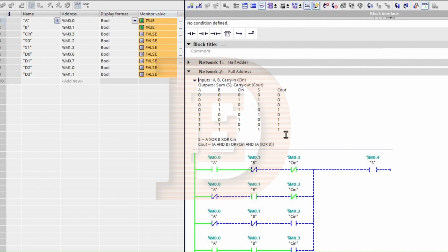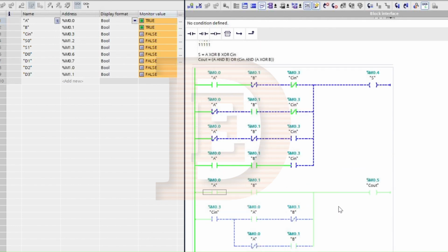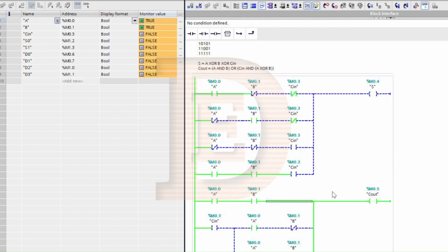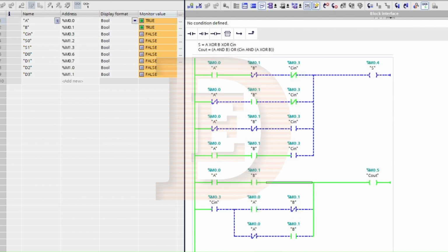So we're gonna say C out is on when both A and B are on, and the C will be a don't care in here because it's either 1 or 0. So we say it's a don't care. And that's basically how we built and optimized the circuit right here.